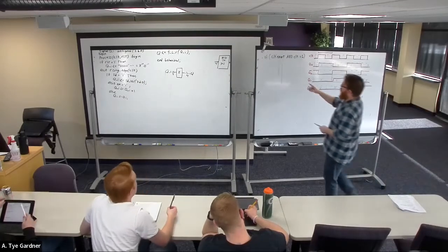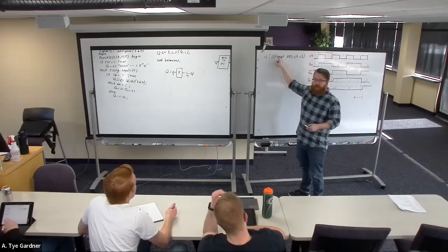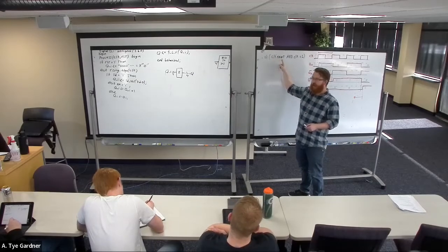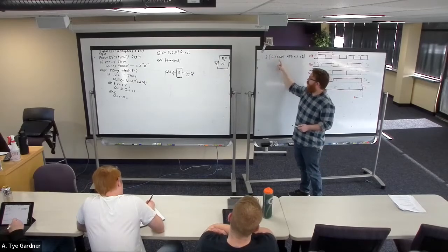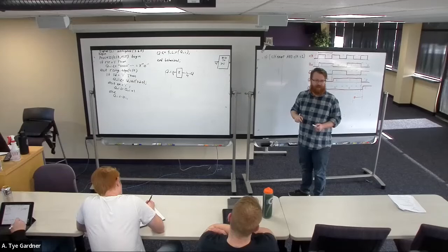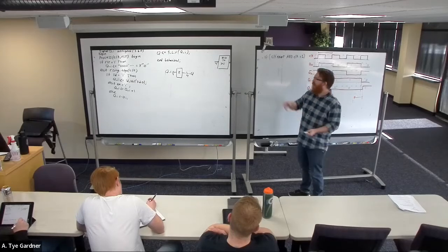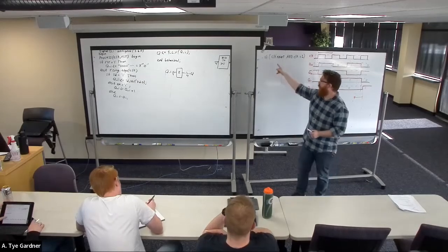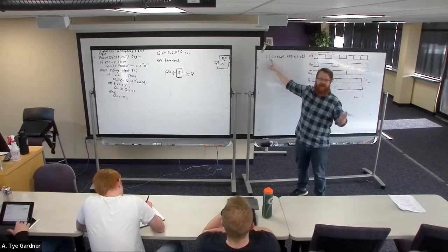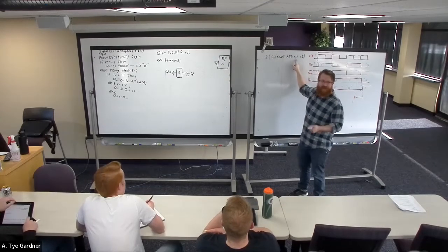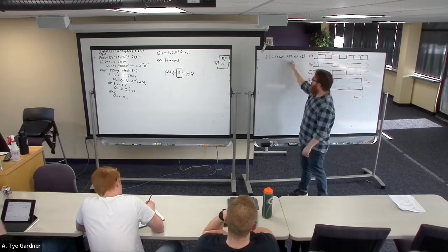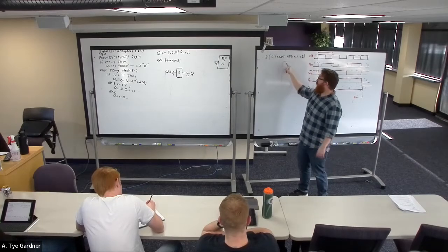The apostrophe, the tick, is accessing properties of this signal. Event is a property that is true if clock has changed. So the process runs, and it asks, as a result of this process running, did clock change? Yes. Did it change and now it's 1? Yes. Okay, right? It's just saying there was a change from 0 to 1 and it ended at 1.